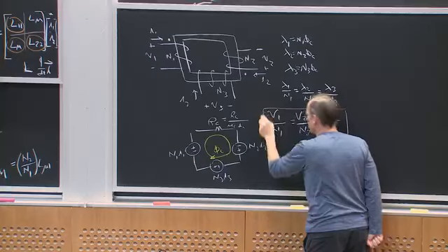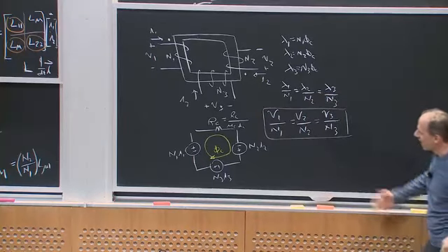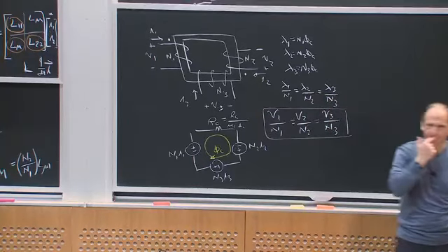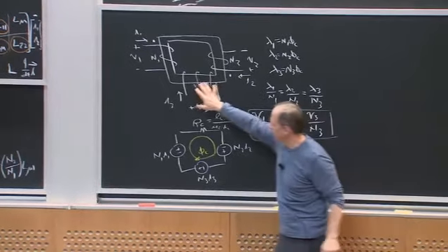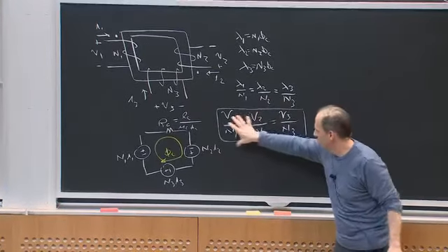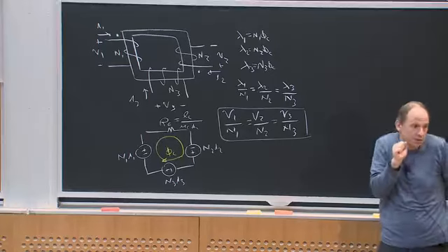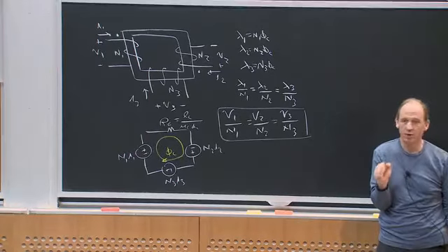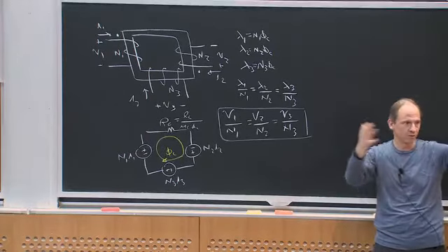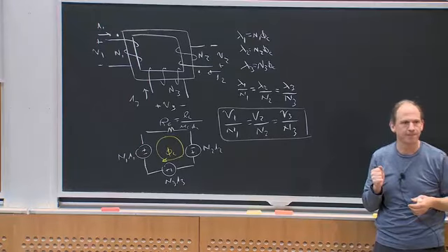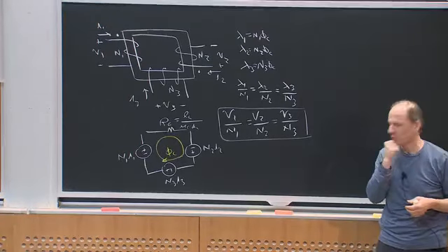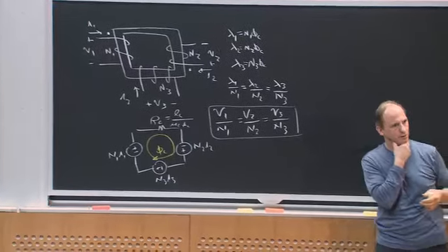So what I've got here by adding my third winding is just another scaled voltage. And we often do that because we often want some ratiometric sets of voltages that our transformer might create. What about the currents?